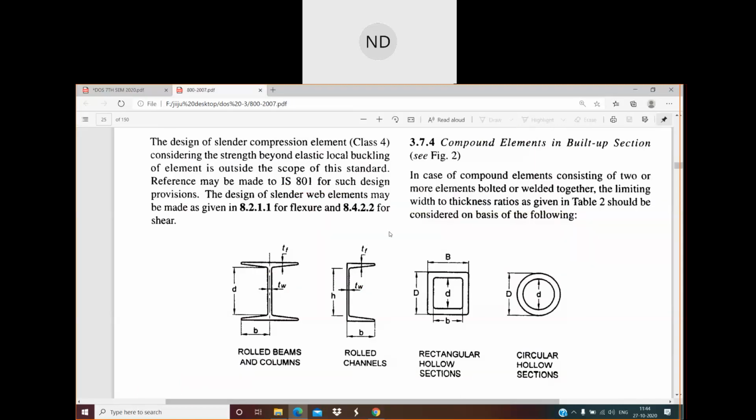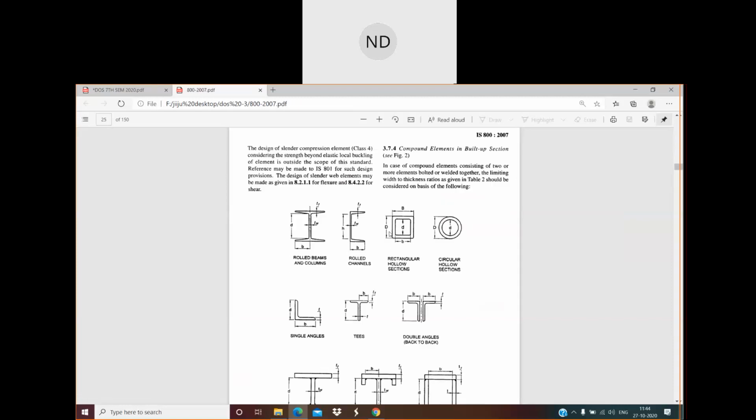So we have got our size of the flange to be 500 into 40. This is our size of the flange. Now we will check the size we have calculated after assuming things. From this we are going to do the serviceability check, from page number 63 of the IS code.